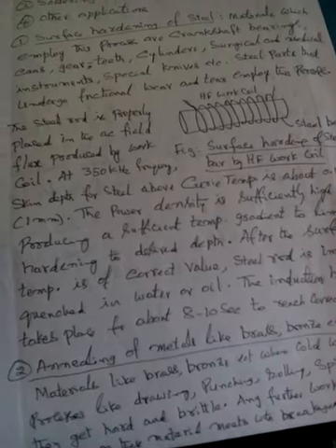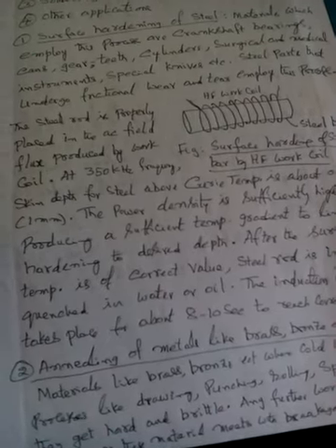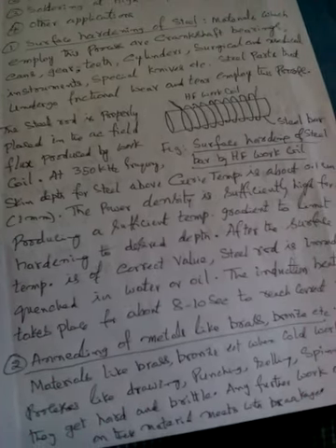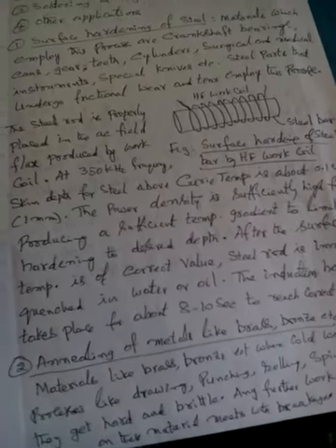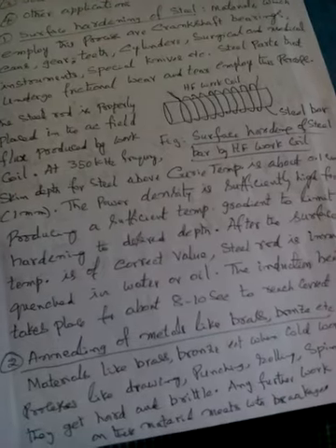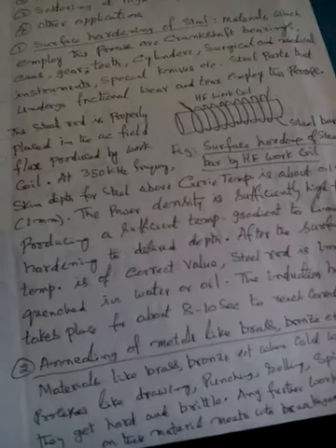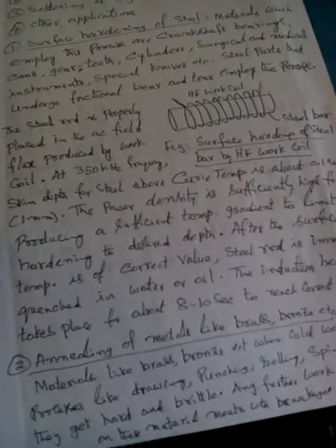Of course, at 350 kHz frequency, skin depth for steel above Curie temperature is about 0.1 centimeter, that is 1 millimeter. Okay, so the heat will go up to 1 millimeter. That is what is skin depth.